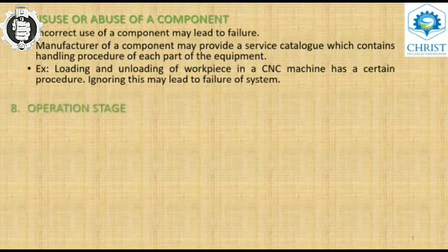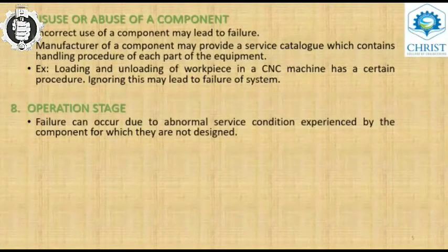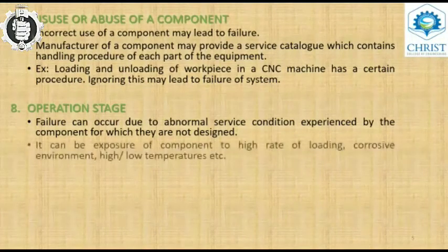Okay. So next is the operation stage failures. The failure can occur due to abnormal service conditions experienced by the component for which it was not designed. Each component or each part is made for a particular ambient condition. So care should be taken while selecting this. It can be exposure of a component to a high rate of loading, corrosive environment, high or low temperature, etc. Okay, as you know.